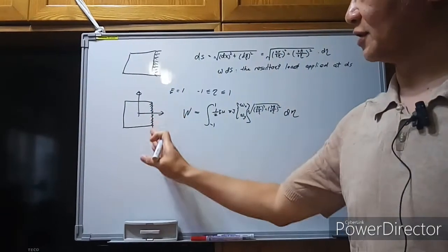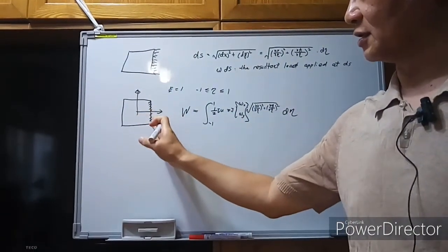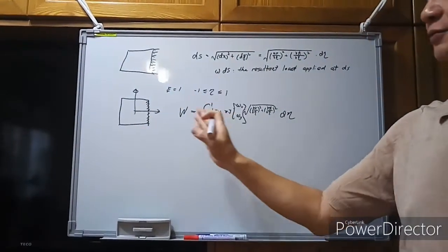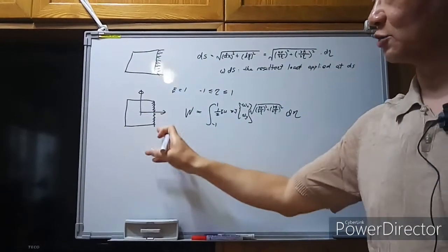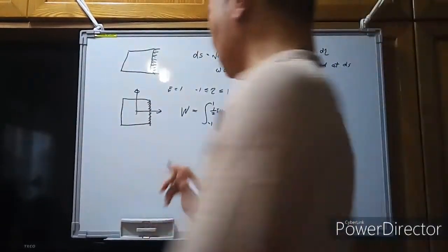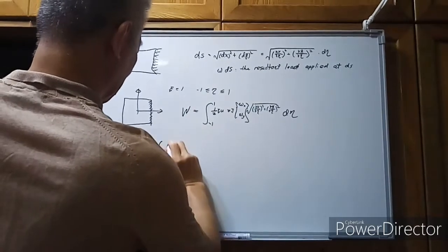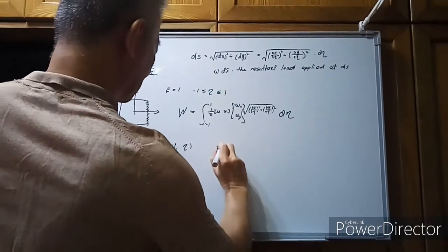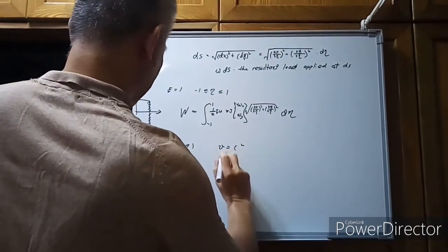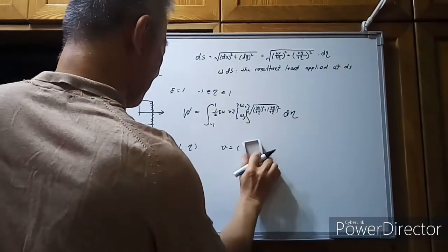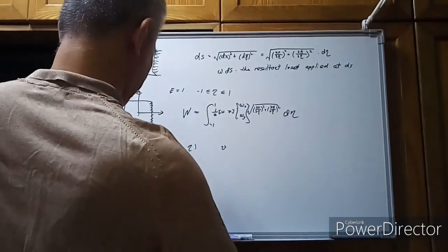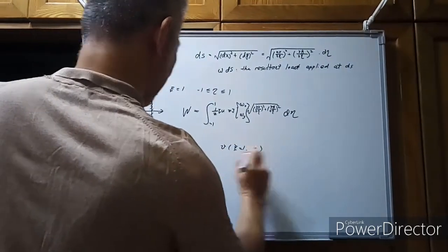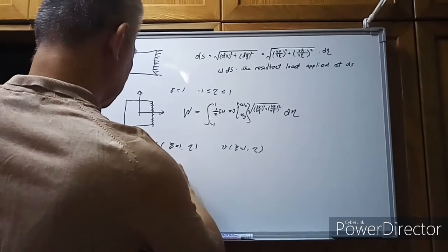Right now it is a very special case if we consider one of the boundary lines, then we just consider the u and v functions at this point. So u is at ξ equal to 1, as a function of η, and also v, which is the summation of u_i times the shape functions.